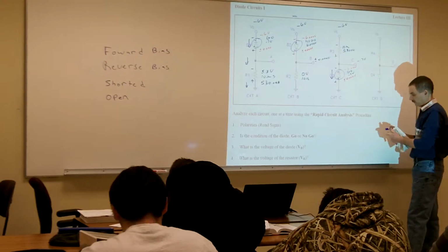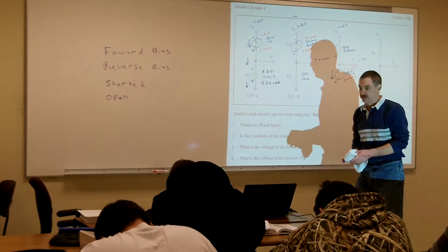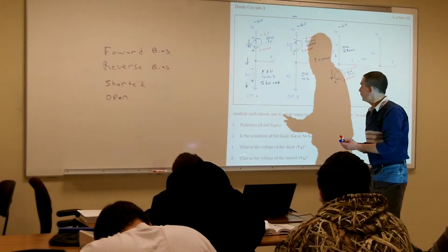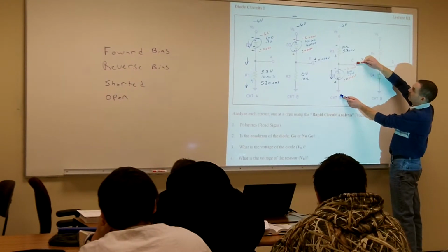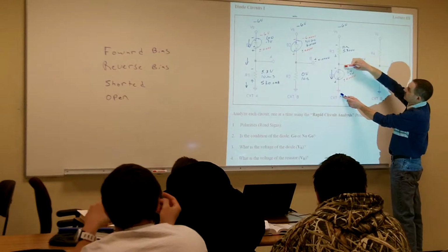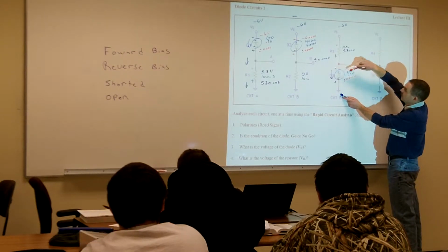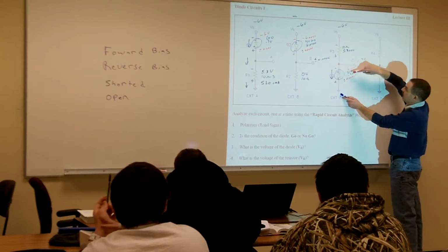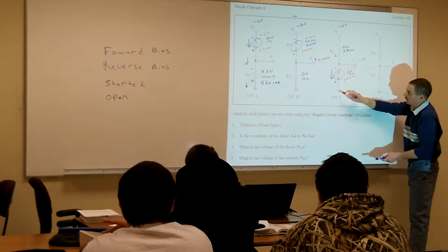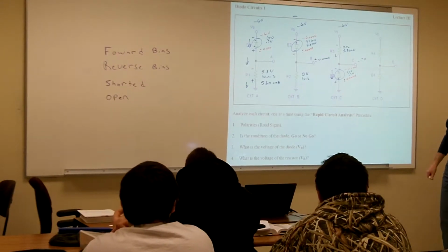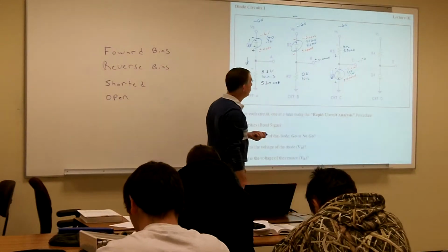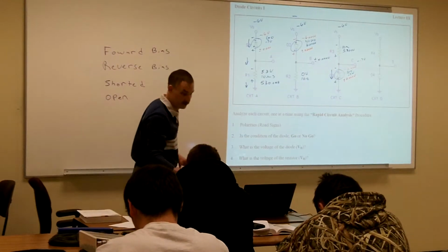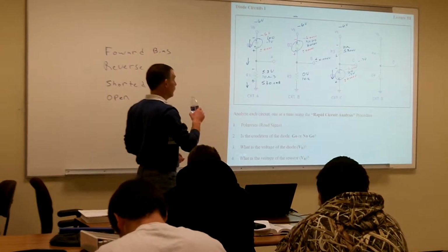So remember, just go back from the old DC days, way back to chapter 4, 12 chapters ago. Take your red lead, bring your red lead down to your black lead. First sign you see is going to be negative. Look at your voltage drop, so you got a negative 0.7 volts and then back up to ground. So yeah, it should be a negative 0.7 volts. Then the current going through the diode is 530 milliamps.